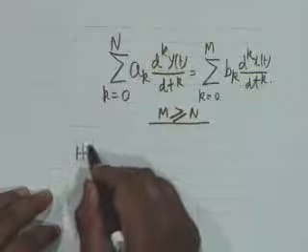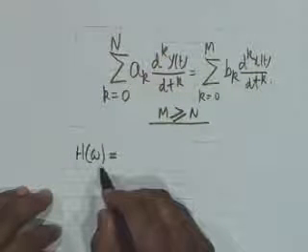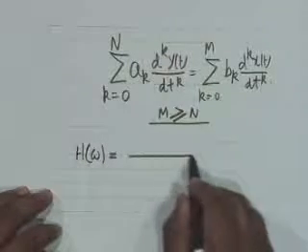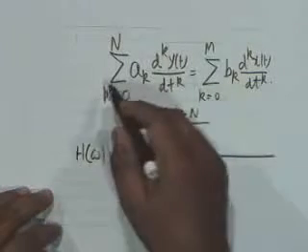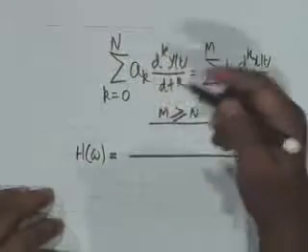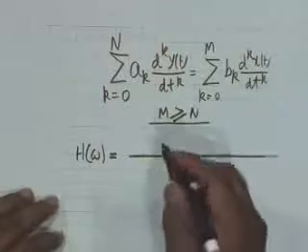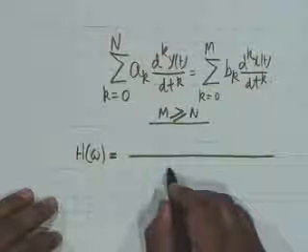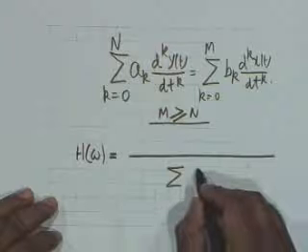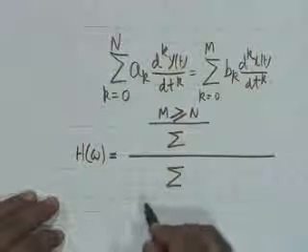The first thing we notice is that H of omega, the frequency response, can be very simply written by inspection. If you take the Fourier transform of both sides, and if you remember that dy/dt transforms as j omega times capital Y of omega, then you simply see that what we shall have is a polynomial in the numerator and a polynomial in the denominator.